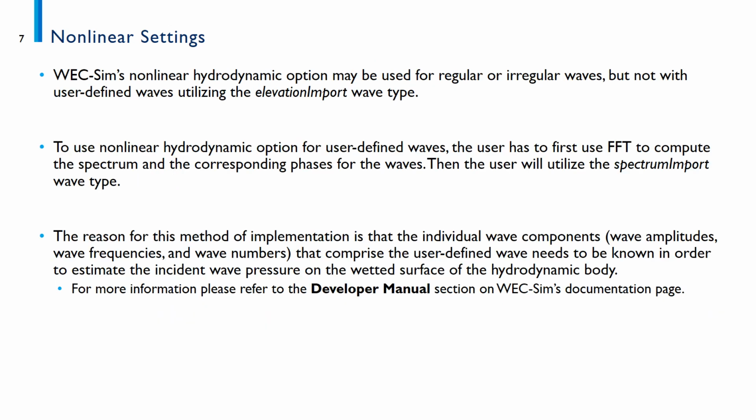WEC-Sim's nonlinear hydrodynamic option may be used for regular or irregular waves, but not with user-defined wave elevation, using the elevation import wave type. To use nonlinear hydrodynamic options with user-defined waves, convert your user-defined wave elevation to the frequency domain with the corresponding phases for each wave component. Then, using spectrum import, you can use the nonlinear hydrodynamic options.